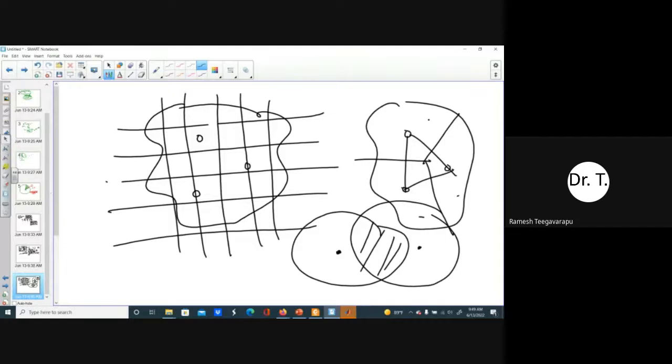So those are X-band and C-band radars, whereas in the United States, most of the publicly owned radars are S-band radars, which have a longer wavelength and a longer range. Just to summarize as a final thought, if you are looking for a gridded rainfall input for your distributed hydrologic simulation models, you are better off having a radar-based rainfall product than a rain gauge-based gridded product.